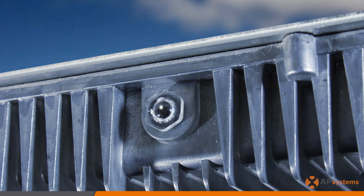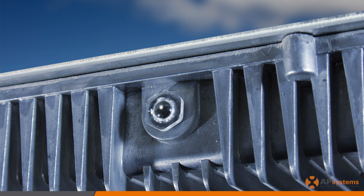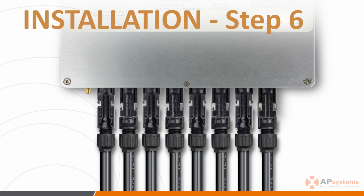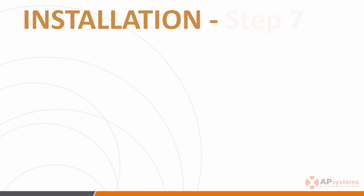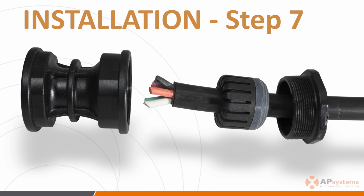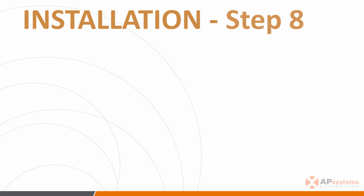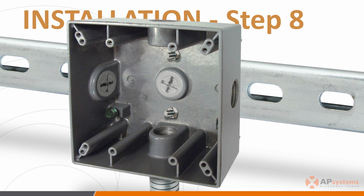Note that the inverter's LED status light will flash red once, followed by 3 green flashes when DC power is first applied to the unit, indicating a successful DC connection. Step 6. Install the Zigbee antennas to each of the inverters. Step 7. Install a protective end cap at the end of each AC bus cable. Step 8. Install the AC branch circuit boxes.